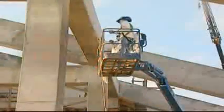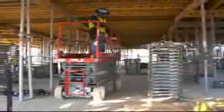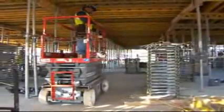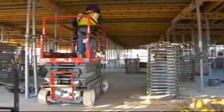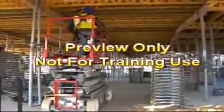Fall protection is required for all personnel that perform work on a lift if they are going to be elevated to a height of 10 feet above a lower level. If the lift is used according to manufacturer's guidelines and all safety precautions are followed, the chance of a fall is minimized. All scissor lifts require fall protection.